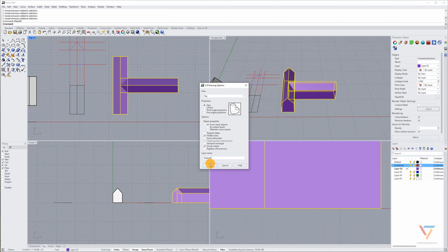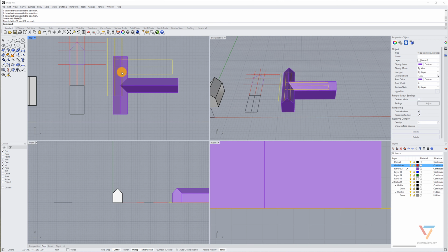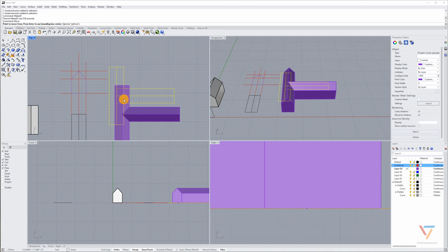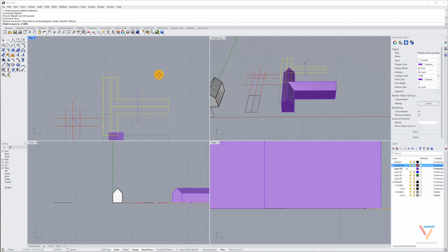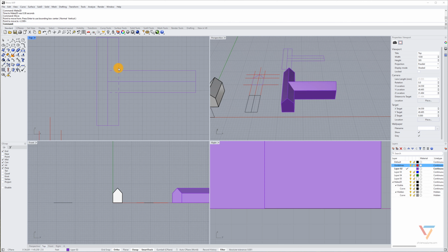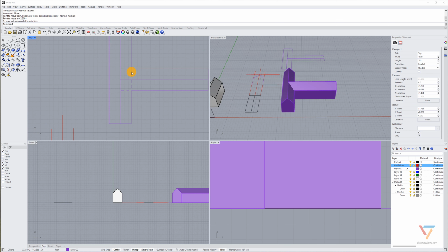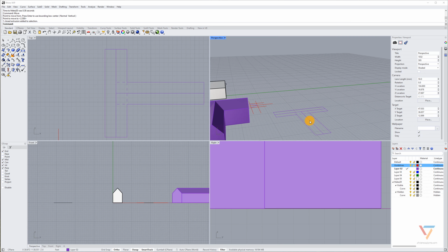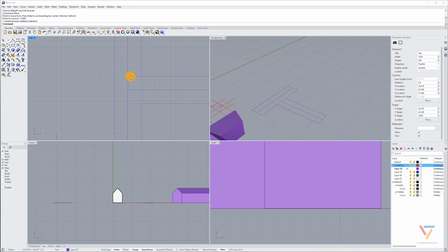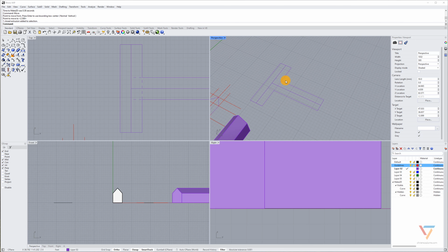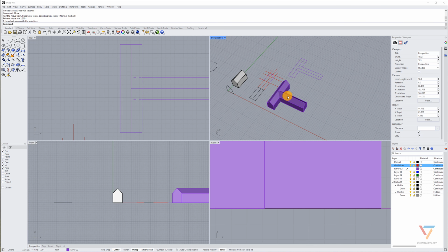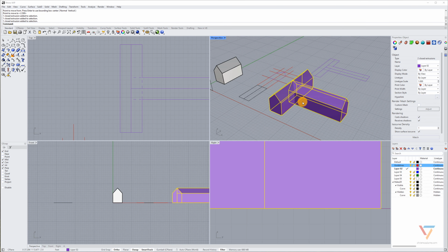to show you that here I can make a new layer called Make 2D, and I will then move this drawing up this way so we can take a look at it, and you'll see that it's the same color from this layer, but Rhino generated a 2D flat drawing, and we see that flat drawing here. The dashed lines you see are hidden lines, lines that we don't see on the object but are hidden within. And this also works in three-dimensional views.